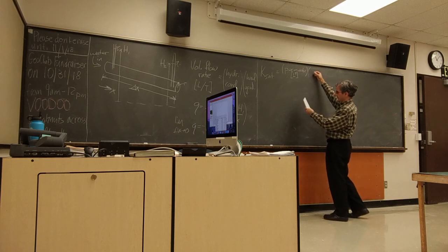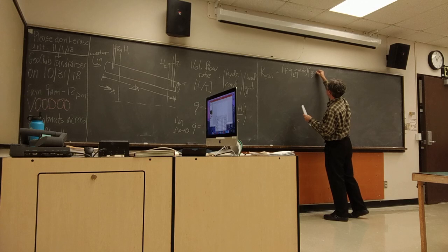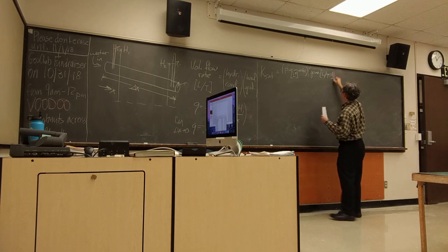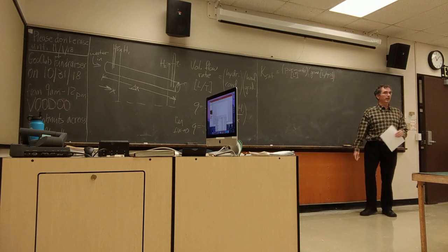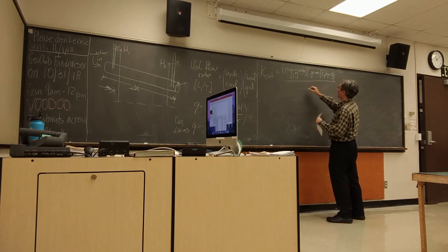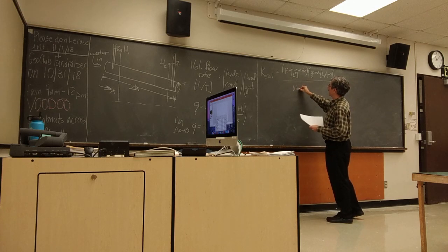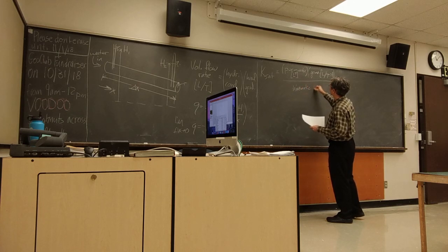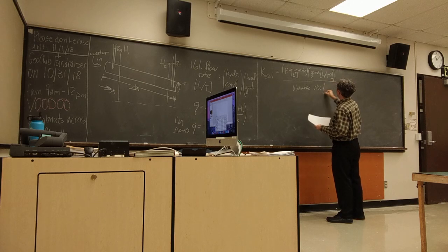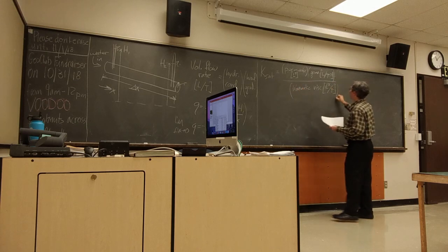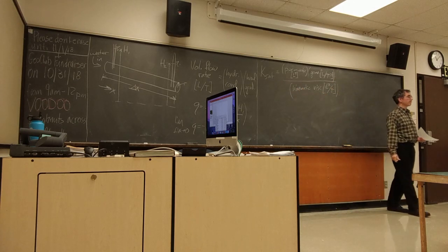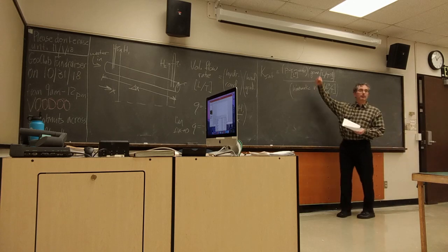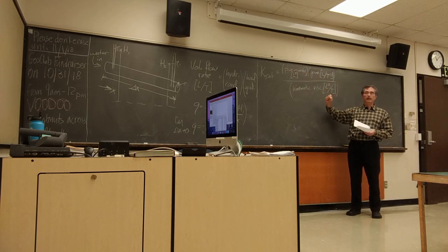It has gravity, which of course is length per time squared, and that's a property of our planet. And it has kinematic viscosity, which has units of length squared per time, a property of the fluid. So we're combining properties of the material, the planet, and the fluid.